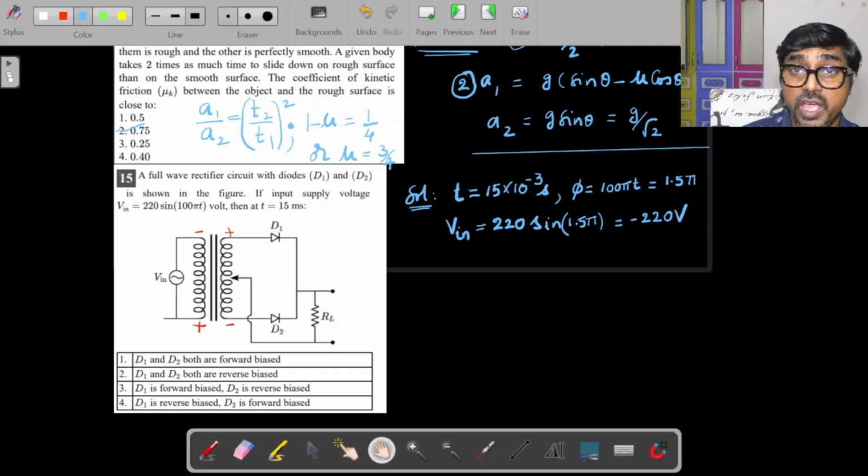So, now we have mutual inductance from the primary coil to the secondary coil in the transformer. This is a transformer concept. So, from input to output there is a phase difference of pi. I am sure you should know that in a transformer, that is one important concept embedded here. If you have minus plus here you will have plus minus, that comes from mutual inductance. I do not want to explain the details there. So, minus plus becomes plus minus there.